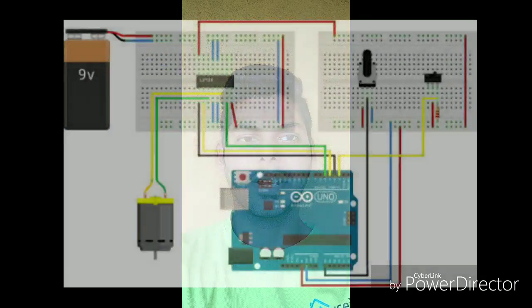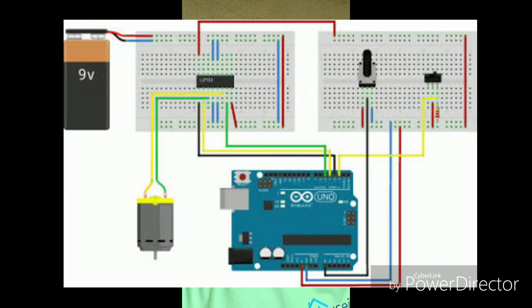Arduino Uno is a microcontroller based prototype board. The microcontroller used on the Arduino board is ATmega328P. Arduino is responsible for controlling the speed and direction of the motor with the help of other components such as the 2N2222 transistors, and it is the main processing unit of the project. The wiper terminal of the pot is connected to the Arduino pin A0. The other terminals are connected to VCC and ground.